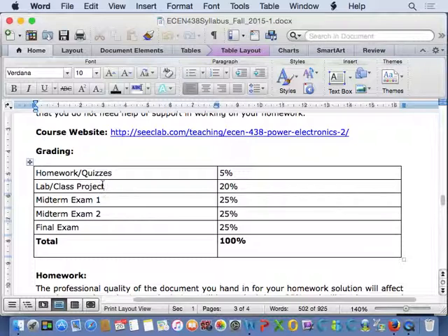So there's typically a UPS in a hospital, for example, or UPS systems, many of them. And then there will also be a backup generator, because UPS systems are based on batteries. How much battery can you put in to feed a building? At the end of the day, you're very limited. You cannot feed air conditioning. You will feed certain places in the hospital, maybe with air conditioning, maybe where they are very needed. Maybe the babies, what do you call it?